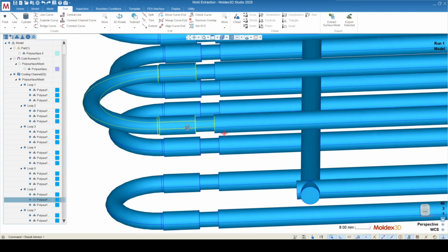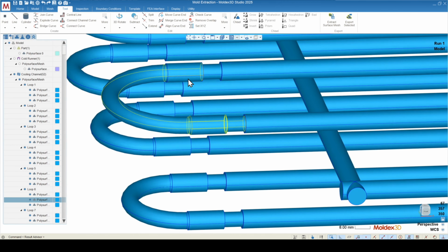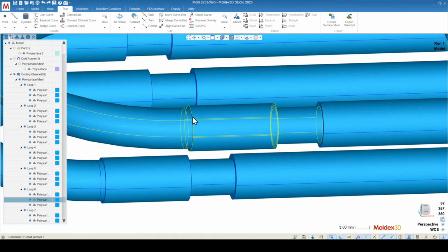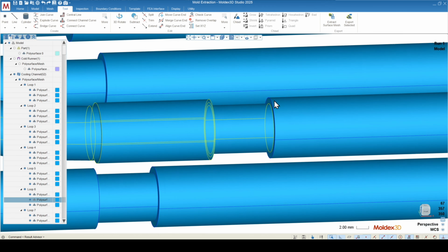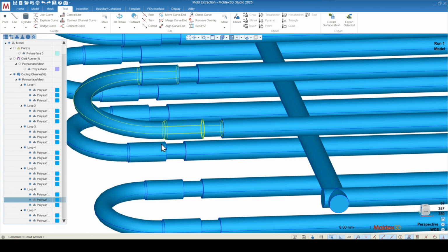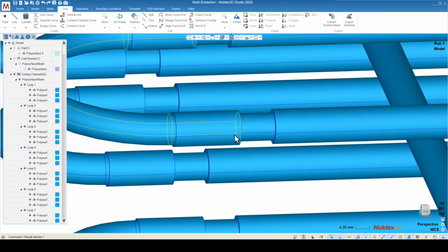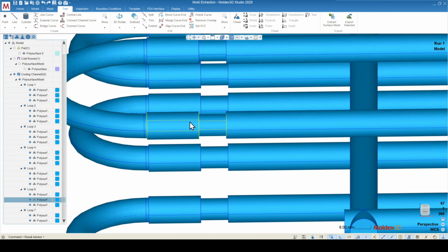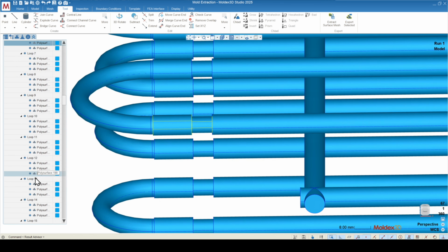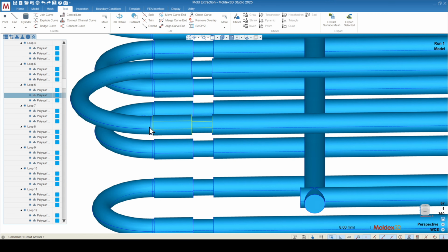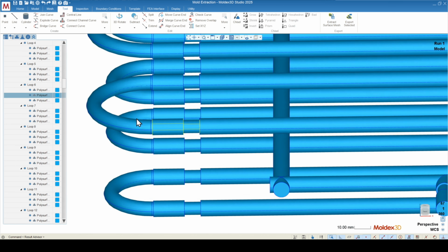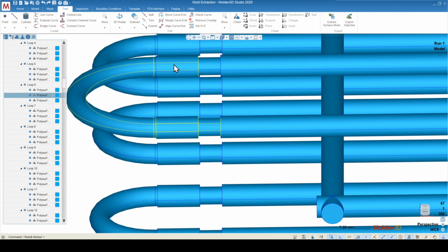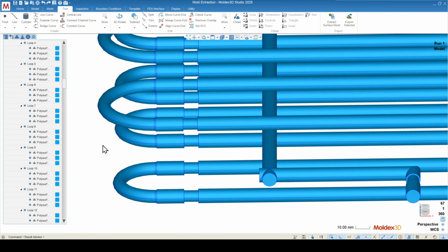All right, so actually what I'm going to do is Boolean these together, because then there's a coincident surface here, and that coincident surface will match here. That's ultimately what I want, for everything to be coincident with one another. If we have an object that's going through another object, this loop wizard is not going to automatically recognize that interaction. So I'm going to go through and do a union for these 3 objects.